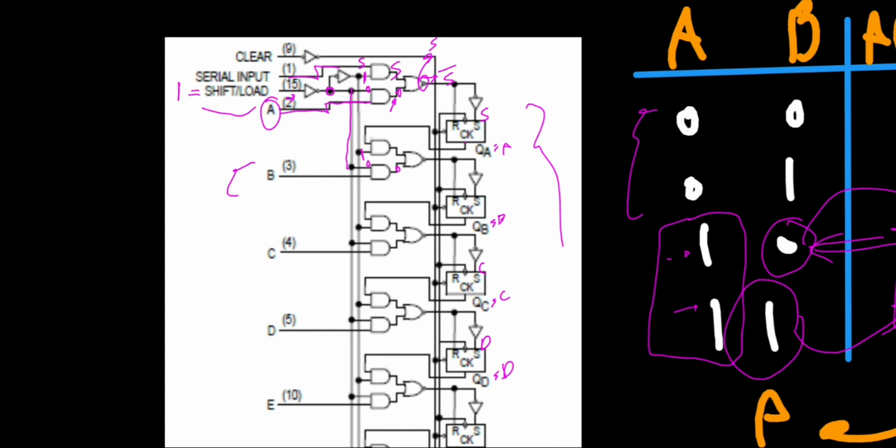but in here, the other input of this AND gate, as you see, is QA, and previously we put a value on the QA. So we have A here, A, and with 1, we would have A here. And A or with 0 would be obviously A, but goes through another NOT gate, which we would have the complement of A, and therefore we would have the A itself here. And the same thing would be applied to all the others.